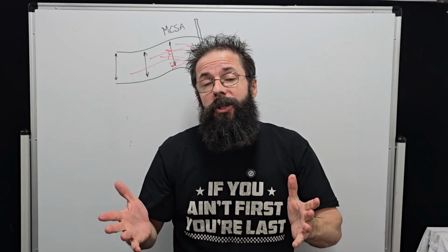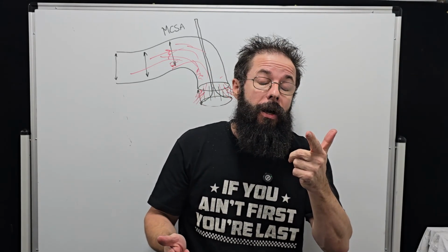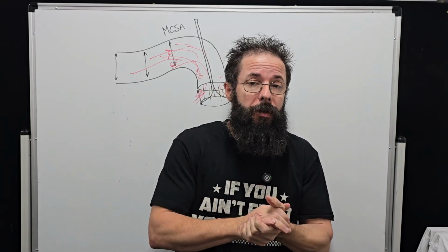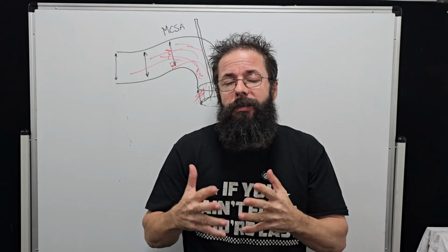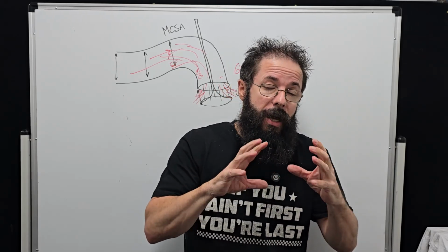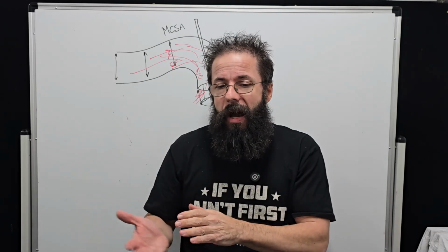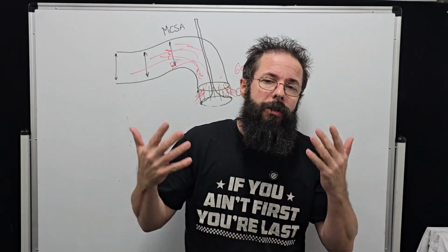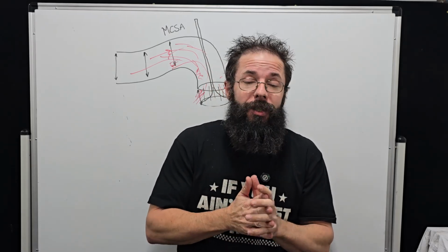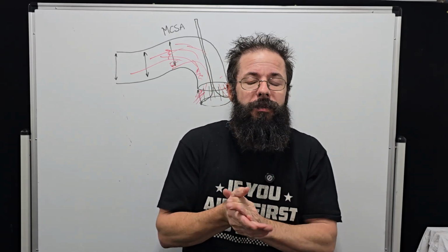All right, so another question I had was from Bradford's garage about Pipe Max and CSA. He's playing with a 3-valve engine, and he was asking how relevant Pipe Max CSA estimates are to 4 valves. One area I see a change in is minimal cross-sectional area, and I was talking about that the other day.